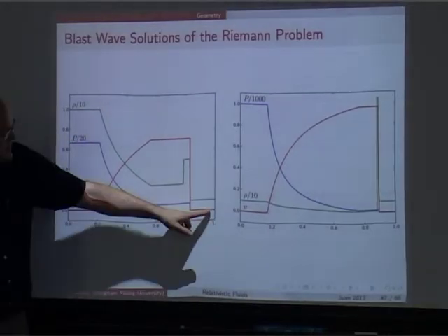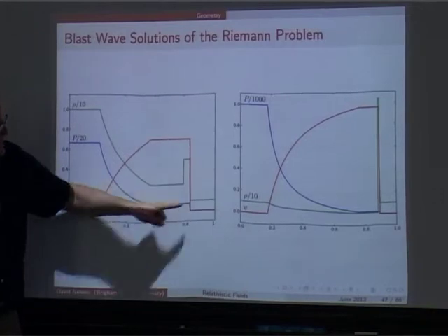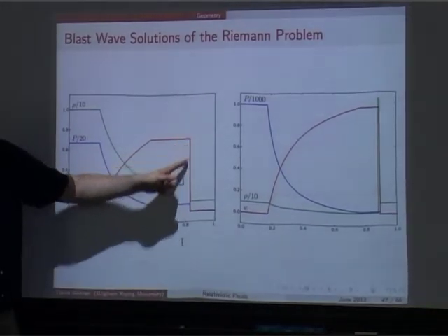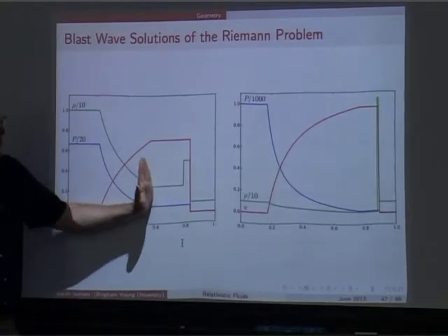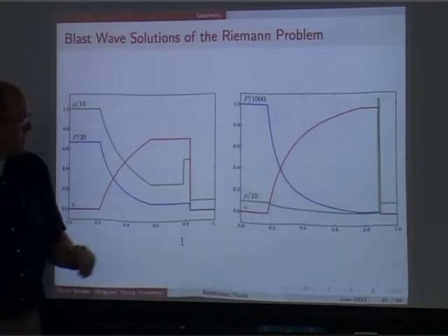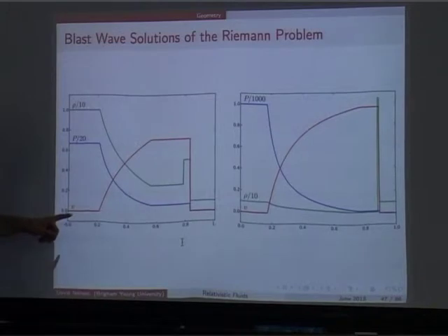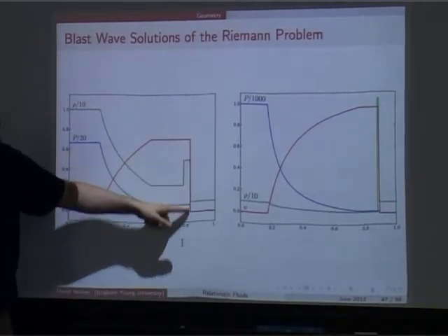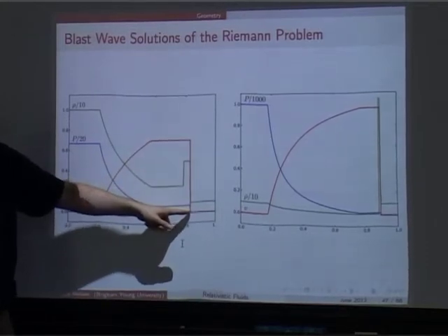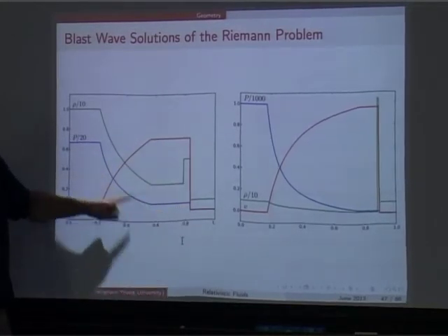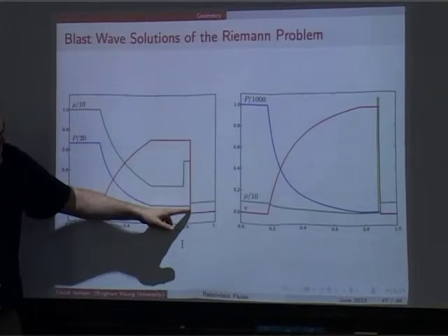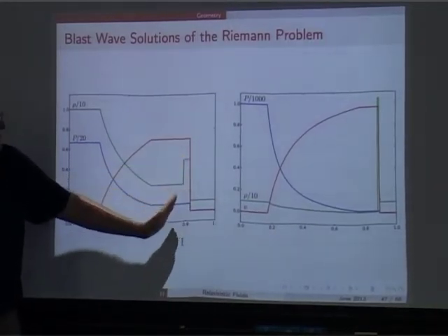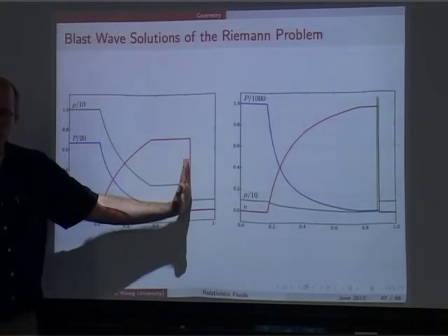And then on the right-hand side, this is the initial right state. What happened is I had a shock that propagated from the midpoint to the right. If I look at my shock, I see the velocity is the red line. I have this discontinuity in both the velocity and in everything, right? Because pressure is the blue line, there's a discontinuity there. You just can't see it. And the green line, there's a discontinuity here. This is the right-moving shock wave.